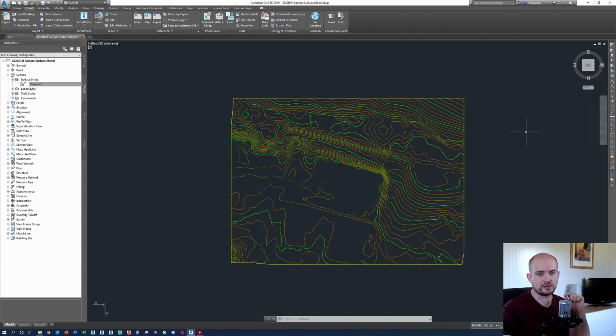And you often have to go and manually edit the points back to what they should be after you've brought in the Excel data. So that's not every point. What happens a lot is that you bring the Excel data into the Revit environment, and maybe 9 of the 10 are correct, and then you'll have these weird anomalies throughout it. So I prefer going through Civil 3D because Revit will basically directly drape over the Civil 3D surface that you've generated, and you know that the point information is correct.